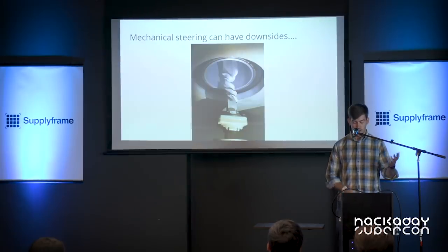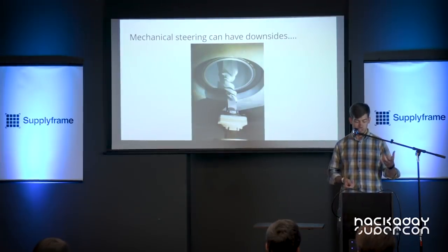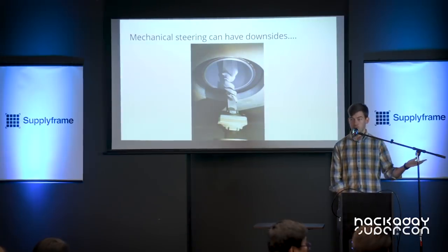However, physically moving antennas around can sometimes incur problems. I think what must have happened here is a limit switch or something failed on an antenna rotator, and the antenna just kept rotating and eventually crushed the waveguide. So we can avoid this with phased arrays.